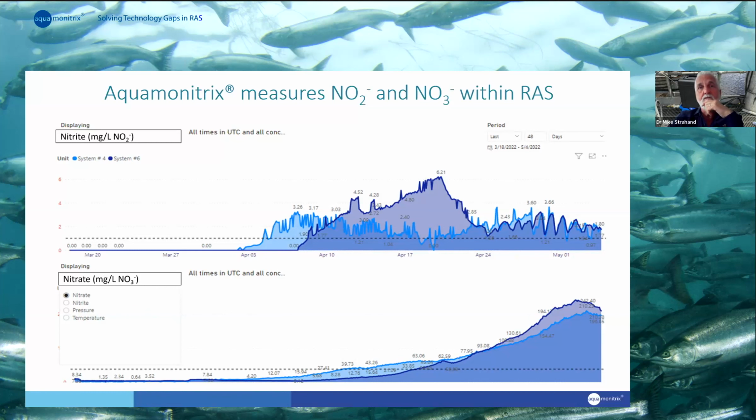So the nitrite on about April the 8th or 9th, you can see it starting to rise to levels which would have caused concern. Instead of dropping off as the filter matured and came into operation, something happened with the biomedia, and the nitrite just went rising and rising until they made their intervention. Then it dropped back down.